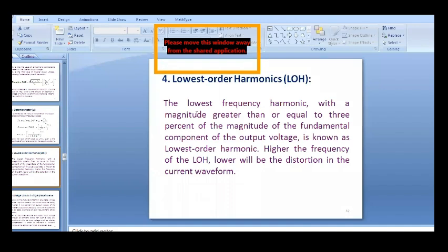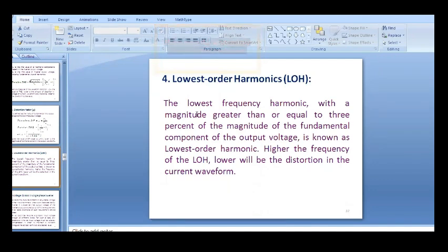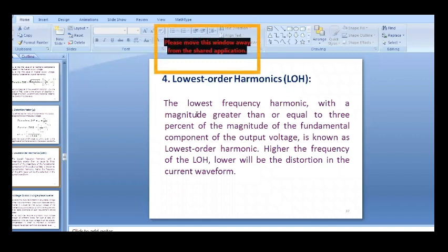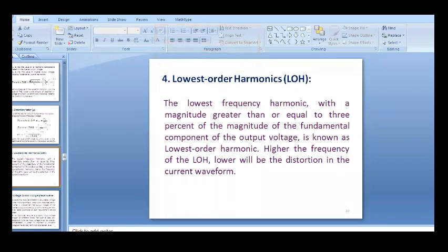When the load and the input DC are identified, then you can find the RMS value of the output voltage, the fundamental component of the output voltage, the output power, the fundamental frequency output power, the average and peak current of each transistor, the peak reverse blocking voltage of each transistor, the harmonic factor, and the total harmonic distortion. So it can be analyzed, and we can do this.